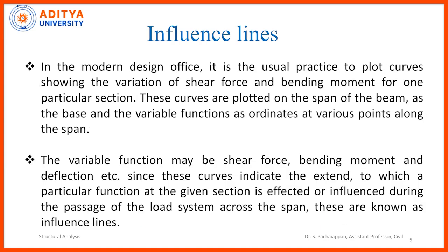In the modern design office, it is a useful practice to plot curves showing the variation of shear force and bending moment for one particular section. The benefit of the ILD is, first of all, that we get the shear force, the bending moment and the deflection as functions of x. In the program, when we put x equal to 1, we get the shear force, bending moment and deflection simultaneously. Here the variable is just the location where the load is currently moving.